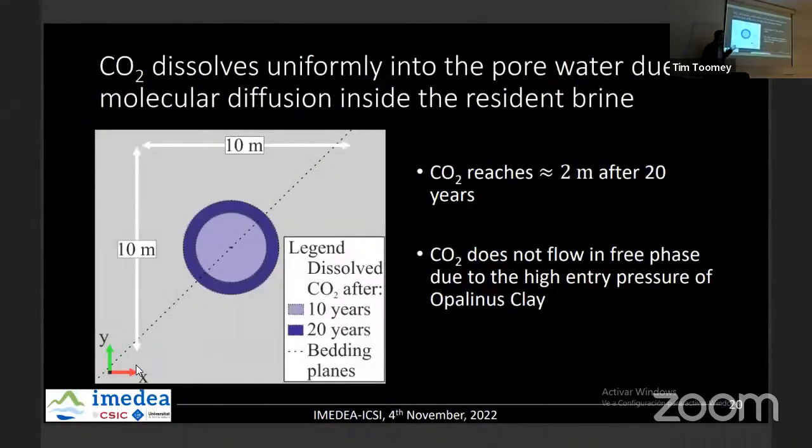Finally, what I wanted to show you was, we talked about the leakage problem before. So now we assess the flow of the CO2 inside this formation of Opalinus Clay. It is supposed to be like a caprock, no? What happens is that, if you remember, I said that initially the liquid pressure was the hydrostatic one, and this at the level of injection was 2 MPa. Then we impose an average overpressure of 3 MPa. So we have a difference of 1 MPa imposed at